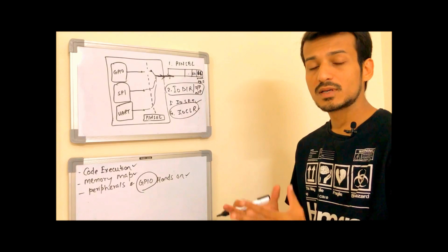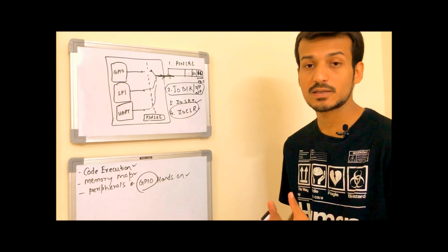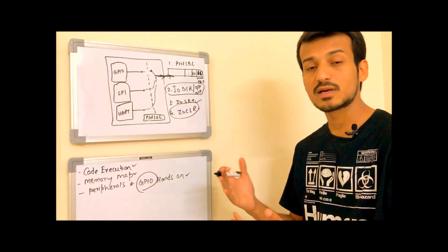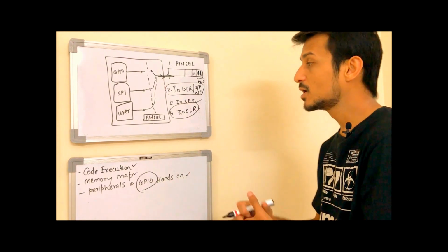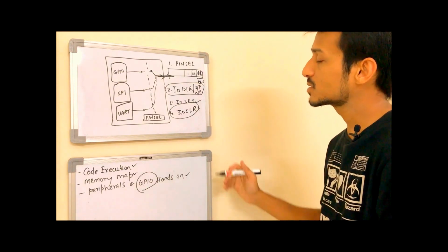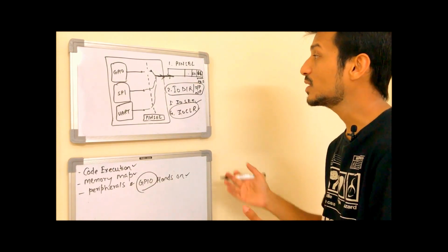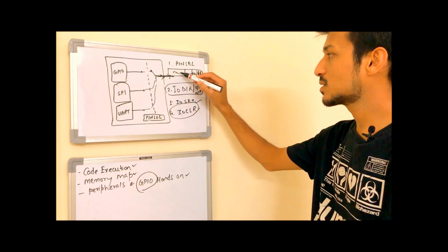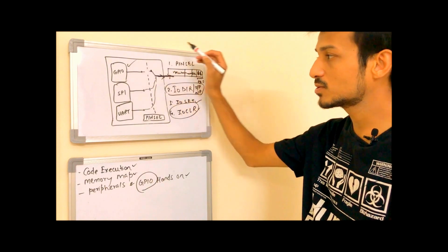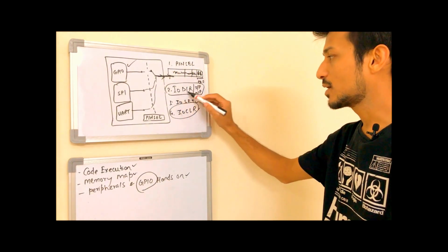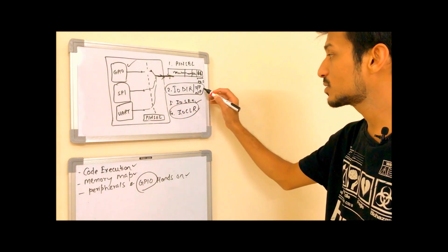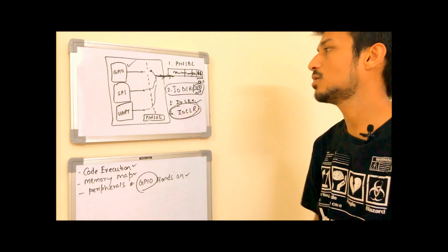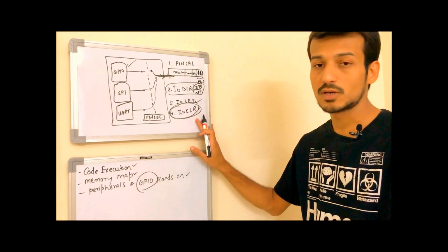By default everything is 0 at startup. When the system boots up, when the system jumps to the boot flash, and from the boot flash the code is loaded, before coming to your main, all the registers are set to 0. What does it mean? It means that by default the pin selection register is completely 0. That means GPIO is selected. By default the IO DIR register is also 0. That means everything is input, and everything is 0 means all the pin state is also 0.